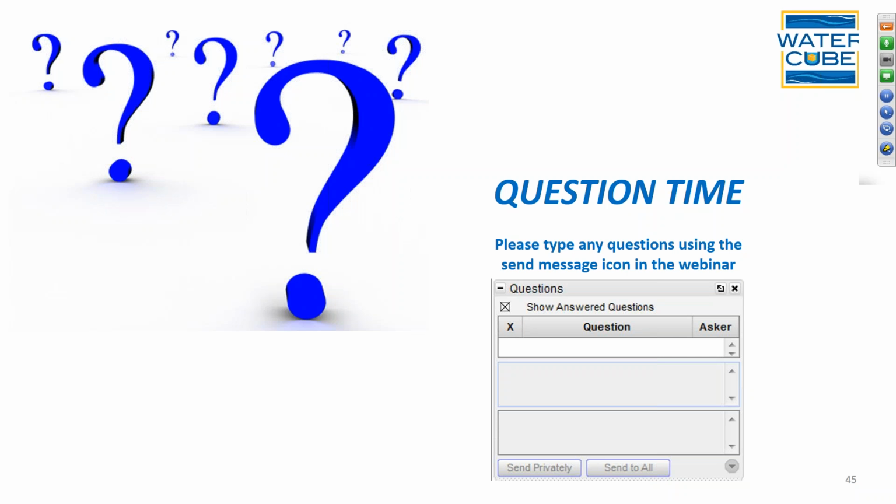And I would just comment, I mentioned art of the possible, and even with the sediment and shear, the best data for calculating shear is right at the stream bed. However, that's where there's limitations with the ADCPs. And if you use everything right to the stream bed because you've used the instrument's extrapolation, what you're going to get is what assumptions you made in doing that extrapolation.